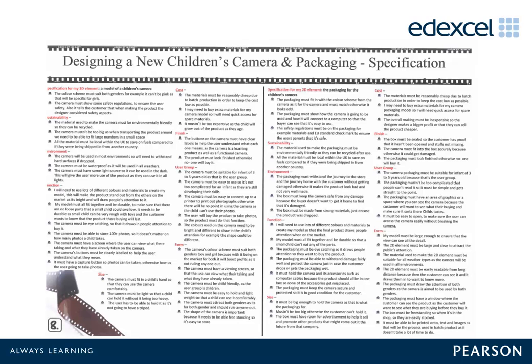A specification should be organized logically, and this can be achieved by using subheadings such as purpose, user requirements, performance requirements, materials, components, size, safety and quality, scale of production, and cost. Specification statements should be technical and measurable wherever possible, so students should ensure that there are several points made under user requirements and performance requirements, as these headings are where such points are made. Specification statements should also be justified to explain why they are relevant to the product.